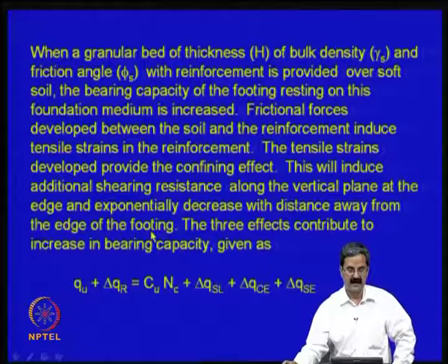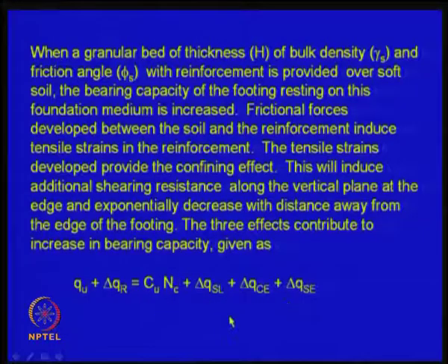So, one is the shear layer effect, the second is the confining effect, the third one is the surcharge effect. All three of them contribute and increase the bearing capacity by these three terms.